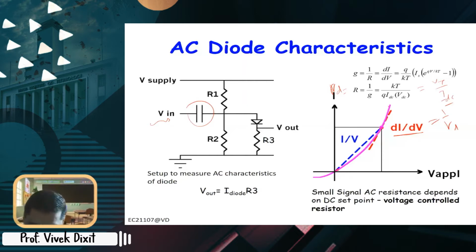The diode is usually represented as this dynamic resistance times VBI. Now VBI is not going to change with V in, the change is very small, so you can probably ignore it. So it will just be a simple voltage divider, and that is for a small signal, not for the total voltage.